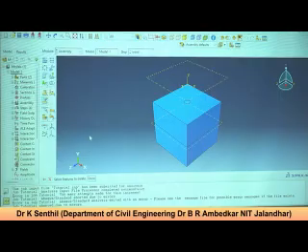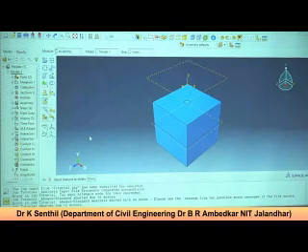Okay, in my experience, I'll tell you, this error may be due to two reasons mainly. The time increments which you have defined in the step module may not be sufficient to carry out the analysis. How will this step time be calculated? Do you know anyone? Step time.